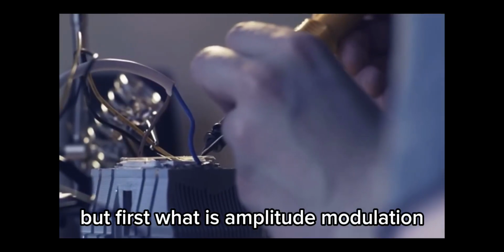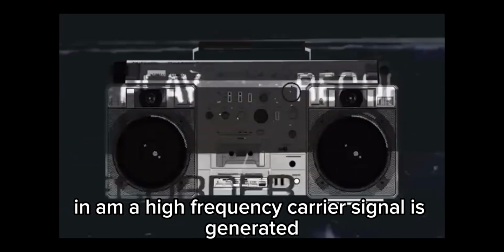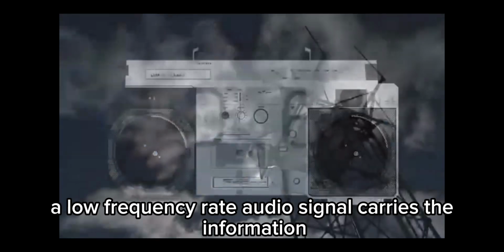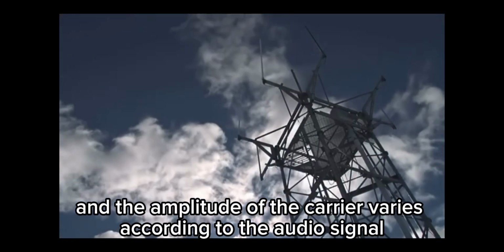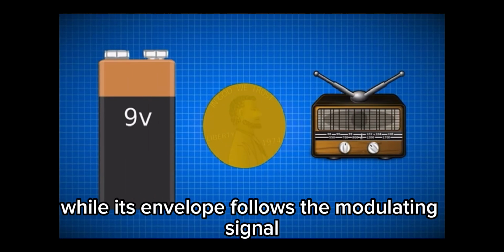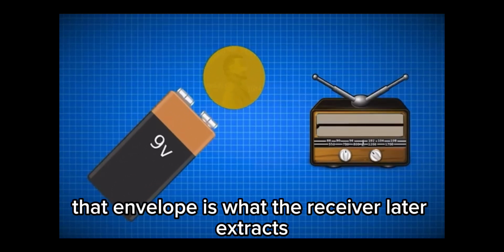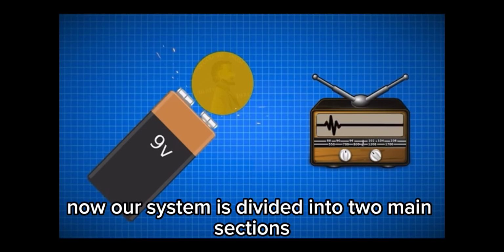But first, what is amplitude modulation? In AM, a high-frequency carrier signal is generated. A low-frequency audio signal carries the information, and the amplitude of the carrier varies according to the audio signal. The frequency of the carrier remains constant, while its envelope follows the modulating signal. That envelope is what the receiver later extracts. Radio waves are undetectable and invisible to human senses, but they make up the foundation of modern connected technology.